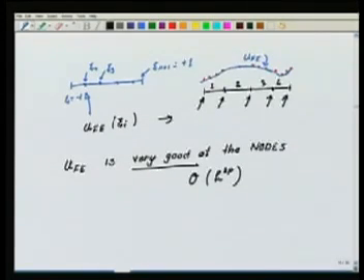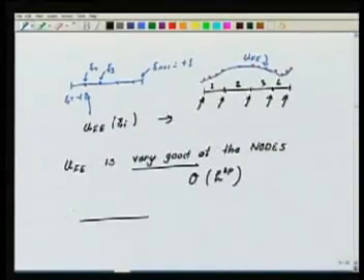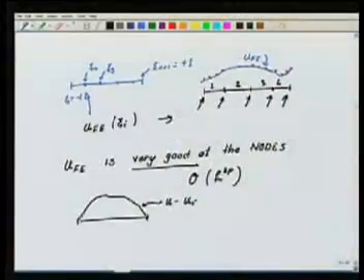Okay. Further, if I plot the difference between the exact solution, if I had access to it, and the finite element solution in an element, it will essentially look like this. So this is u minus u_FE. Okay. Now imagine that the size of the element tends to 0, that is I am shrinking the size of the element.